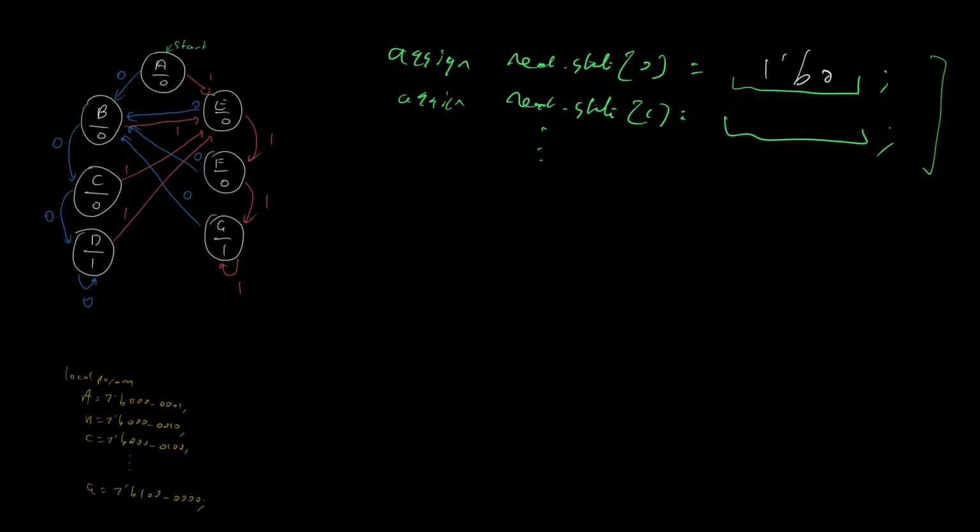So bit number 1 corresponds to state B. So in state B, we're asking ourselves, how can we end up in state B? It's worth pointing out this thinking is opposite to how we do it in our canonical form. Normally, we've got a case statement that works out which state we're in, and we say, if I'm in state A, where can I go? But if we're doing this one-hot coding by hand, we're doing the reverse. We're saying, how can I end up in state B? We're not saying, if I'm in state B, where do I go next?